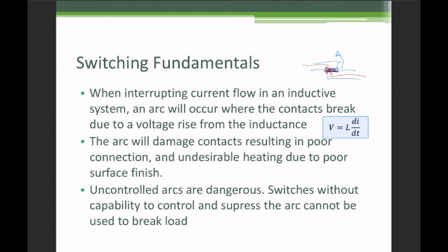So when we're talking about a switch, we're talking about how this switch, or whether this switch, can manage the arc. If it doesn't have the ability, and there's our first differential, if the switch does not have the means to manage the arc, you can't use it to break load because you'll end up with this uncontrolled arc and kaboom.